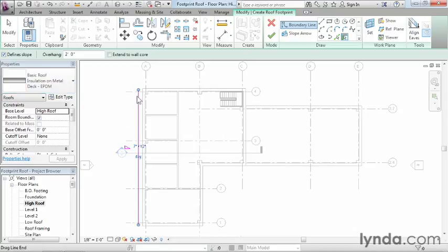So what you want to do is think of this sketch line as almost like a piano hinge. So if you imagine that that line is hinging, then the plane of the roof, instead of being flat right there at that edge, is actually going to slope up from that edge. And how much it's going to slope is controlled by this number right here. The default is this very strange fraction, basically 7 and 12.